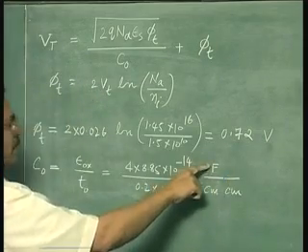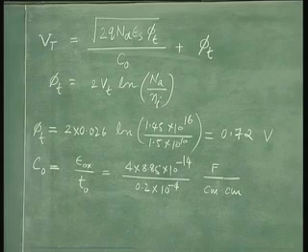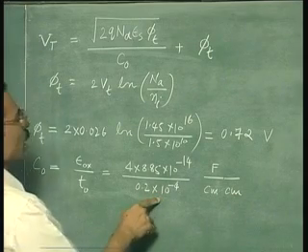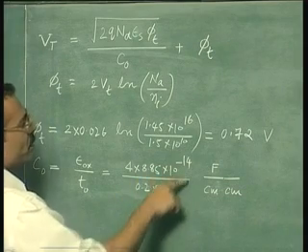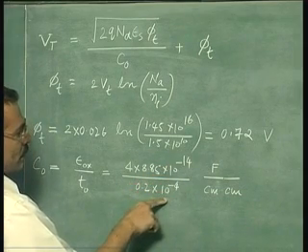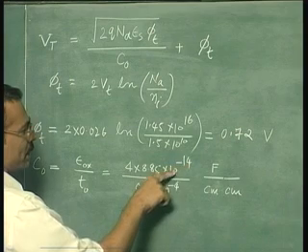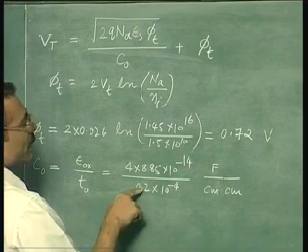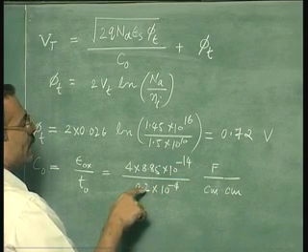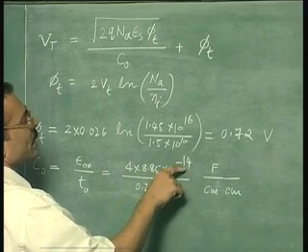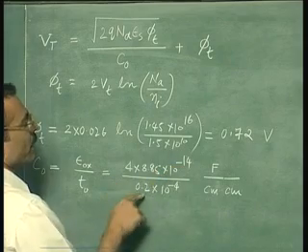So you see the capacitance is farad per centimeter square. Now this value, if you see, it will be of the order of nanofarads, okay, because this 10 power minus 4 goes up, it becomes 10 power minus 10, but then you have 0.2 here, so multiply numerator and denominator by 10, this will become 2, and here you will have 10 power minus 9.